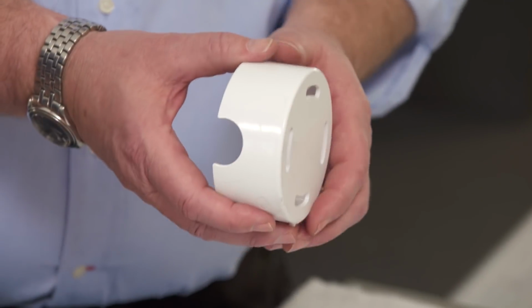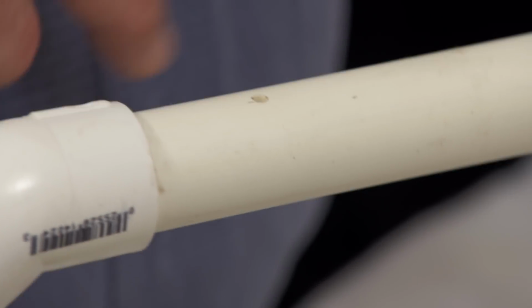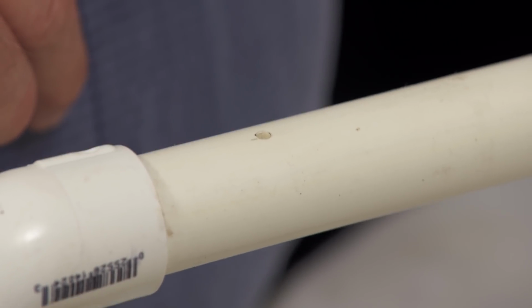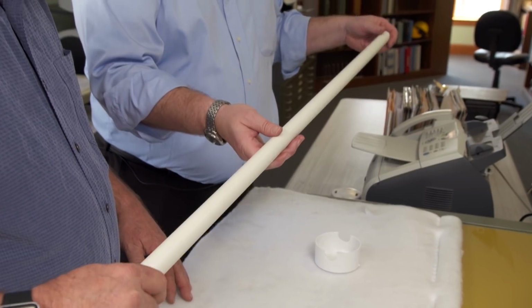Yes, we can. Conventional field has a 4-inch pipe. Oh, yeah. And it would have 2 holes in it. Right. Some water dribbles out here, covered in stone. Covered in stone. Yeah. But in this situation, we can use a smaller pipe. Wow. With very tiny orifices. Look at the size. That's it? Yep, these are the orifices. Wow. 1/8-inch holes. And they're about 2 feet apart or 15 inches, depending on the size of the system. All right. And that's it.